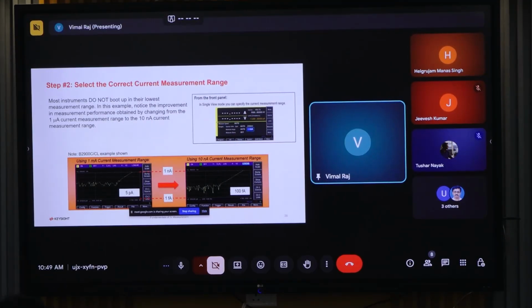What will happen is, the easiest way of measurement is, for example, if you have a diode connected and you do it in auto range, then the auto measurement speed will be auto. In auto, the measurement range will switch automatically and it will take some time delay, but it will not be noticeable because it happens in microseconds. If you put it in auto, the equipment will take care of the speed based on the range.